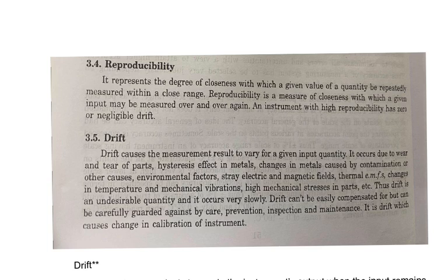So what can you summarize here about drift? If you understand, you can write it in your own words. Drift causes the measurement results to vary for a given input. It is mainly due to wear and tear of the parts. It might also be due to environmental changes and contamination.